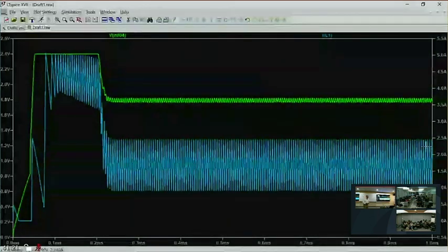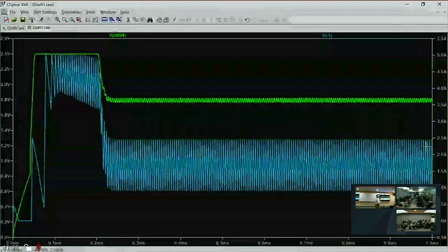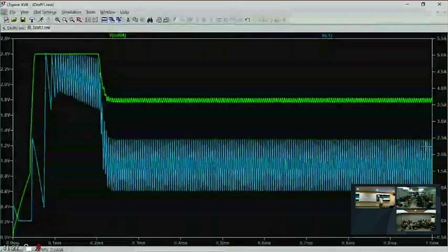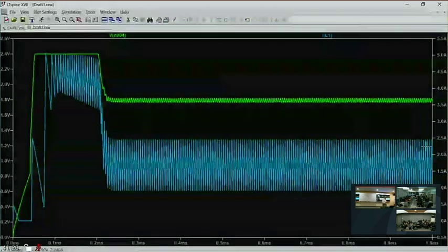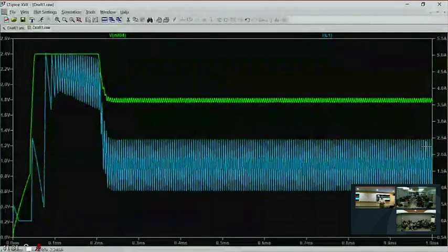And since the reactances are all piezoelectric, I mean, the capacitors are piezoelectric and the inductors are magnetostrictive, you'll hear this power supply make noise, right? A power supply should be seen and not heard, right? So it's not good. Anyway, none of that's good. You don't want that to happen.